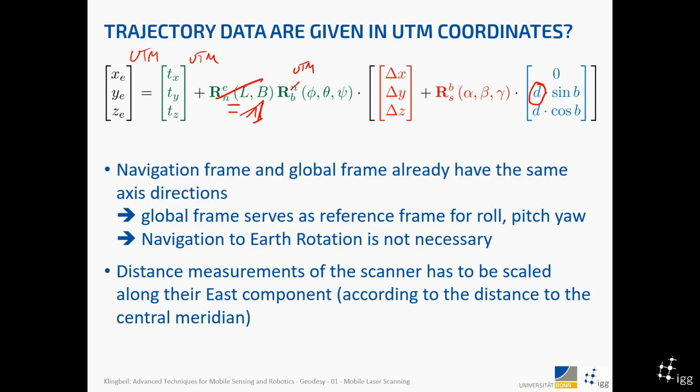It turns out that if you do that with laser scan measurements in the order of 30, 45, or 50 meters, this can be neglected, or you can assume a constant scaling factor in a certain area. So the change of the scaling factor can be ignored, but the absolute scaling factor shouldn't be ignored if you consider millimeter accuracy, right? If you're anyway in the centimeter range, that's not a big deal. But if you're interested in millimeter accuracy, you have to consider this.